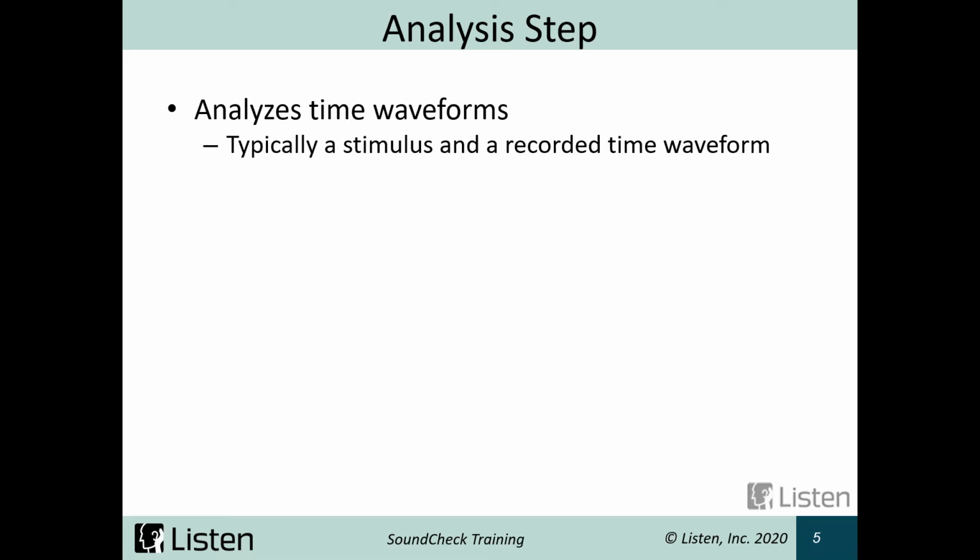Alternatively, if we were doing open loop testing, where we were recording on a different device, we could recall wave files into SoundCheck without actually having an acquisition step and analyze it the same way. We also would have the option to group different waveforms together and analyze them in one step. If I had an 8-channel mic array, I could group all of those microphones together, send those into the response section of the analysis step, and my analysis editor would give me 8 different curves for those 8 different waveforms.